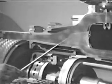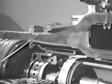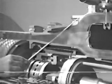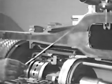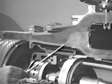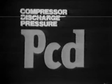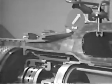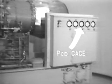This diffuser pathway is formed by the diffuser case, the compressor bearing support housing, and the turbine bearing support housing. At the rear of the diffuser, air pressure is the highest in the engine. Since this pressure is most important in monitoring engine performance, it's given a special name, the compressor discharge pressure, or abbreviated in engineering terms, PCD. PCD is measured at the turbine bearing support housing and is an important display on the engine gauge panel.